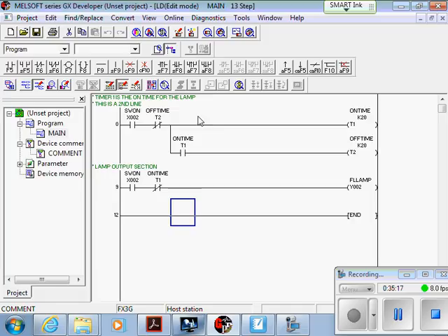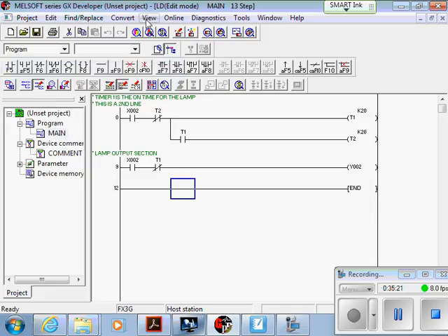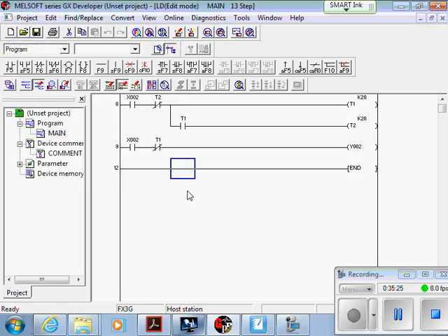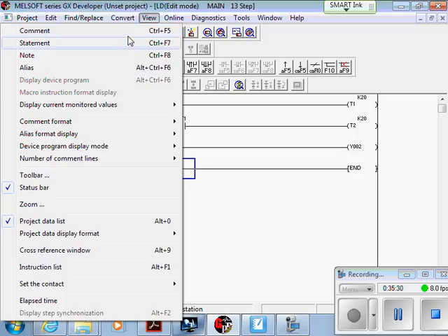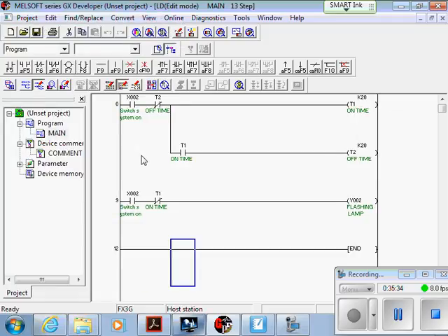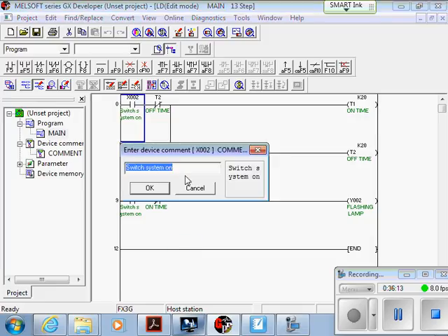What I then have to do, the default, let me turn this back to no alias, no statement. Right, so that's where you are until you turn on, first of all, the full comments. Notice how that's taken up more room on the screen now because the comments are turned on. Also, if you look at this one that I changed back, that's split the word system. It's got S on the top line and then the rest of it's on the next line. It's not formatted very well. It's actually easier to get those looking right if you edit them on the ladder diagram. You can do the statements and edit the comments on the ladder diagram. You just go into this comment mode, double click there, and you get this dialog box up, and this actually gives you an idea of what it looks like on the screen.